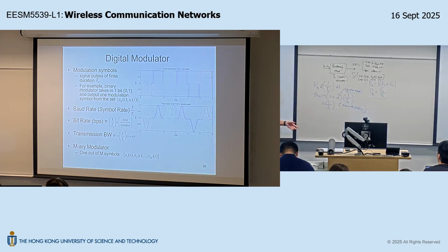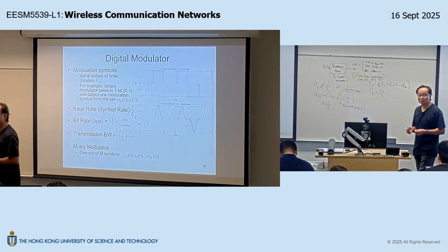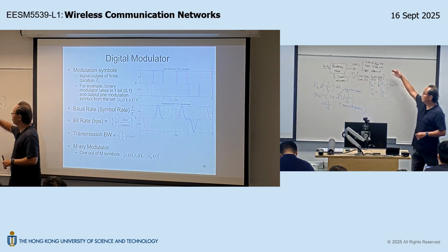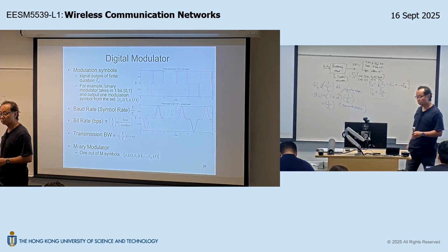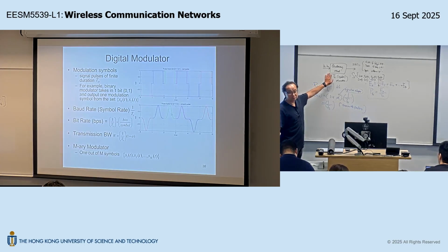So this is amazing. Now, of course, the average power also needs to be modified. Instead of 1/2 in this case, we have 4 possibilities. So it will be 1/4, like this. Is that okay? So 25% for each combination. So that would be the modification needed when we upgrade to quaternary modulation. Is that okay? Now, sounds too good to be true, right?